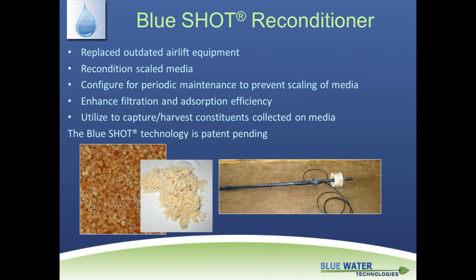Now, when we're doing a lot of these metals removal applications, we're having to adjust pH again to target specific adsorption isotherms, as I mentioned previously. And that can sometimes be a good recipe for scaling within the media bed.